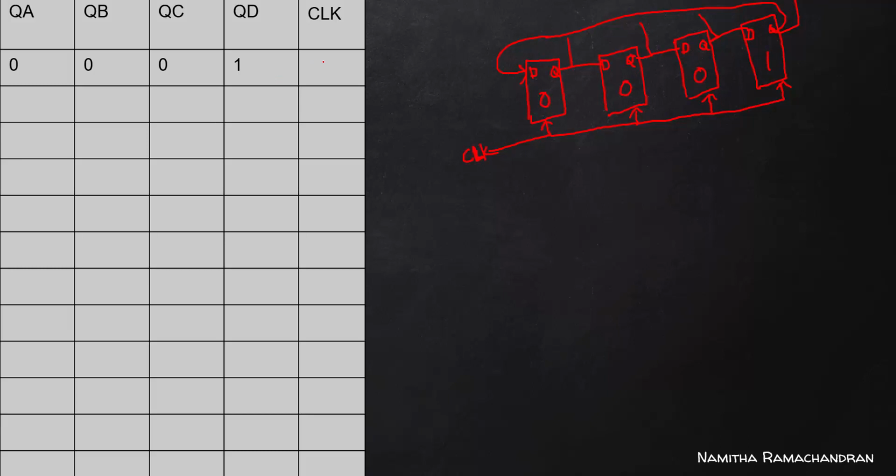After this initialization, suppose we apply the first clock input. Then the shifting will happen like this. The last flip-flop's output is shifted to the first flip-flop. The previous 0 comes to here, this 0 comes to here, this is shifted to here. In the next clock pulse it will shift to the next position, and the pattern is like this.